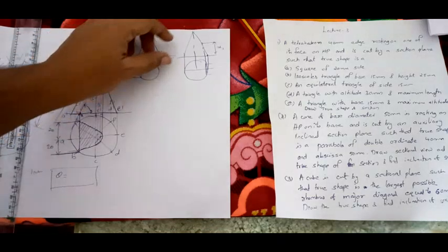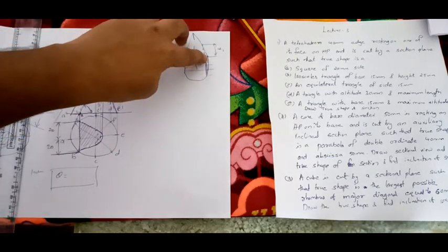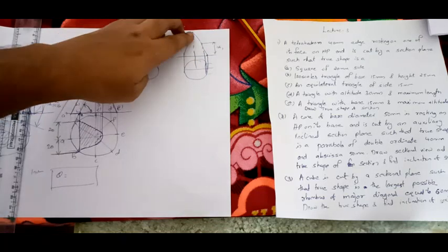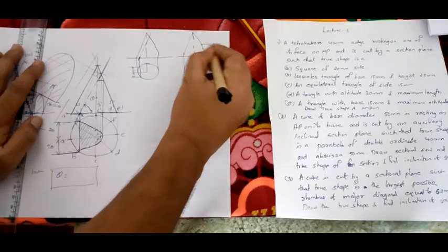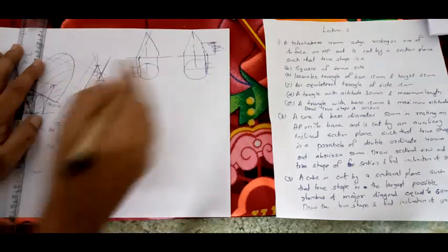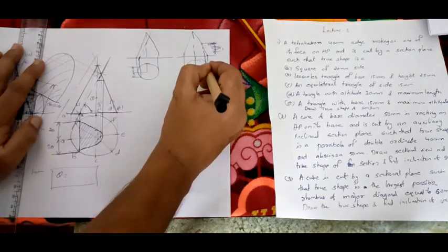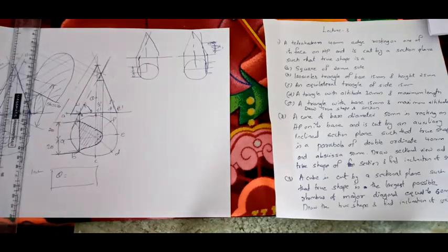They have given the abscissa distance, so you have to find this point from the right extreme point, extend that line, and touch the axis line completely. If they have given the height, there is no need to give the abscissa. You can draw the front view and top view, then the double ordinate. After that, project it just perpendicular.